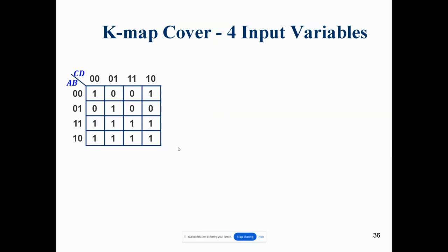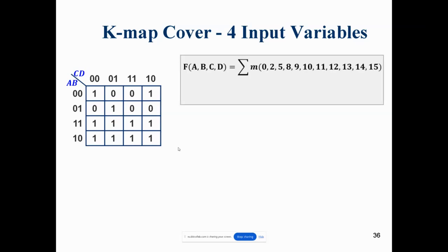So now we have a K-map. Now we have a function of 4 variables. Okay, now look at here. Whenever we want to solve this problem, we are interested in the larger group. Where is the larger group? Can you see where is the larger group? So now this is a larger group. We first need to cover the larger group. So now this is the expression. What is this? It is a sigma of 0 to 5, 8, 9. This is the sum of minterms form.